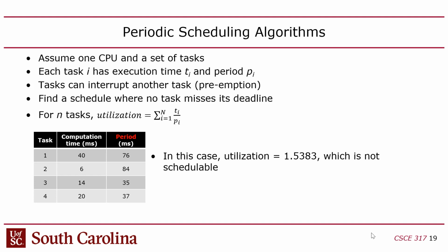They're normally preemptive, meaning that tasks can be running and be put to sleep and let another task run, and then we'll come back to that task and finish it later. That's preemption. If you don't have preemption, the scheduling becomes even harder. So you might think, well, preemption really complicates things. No, actually, preemption simplifies the scheduling algorithm. And then we talked about EDF scheduling and RMS scheduling.